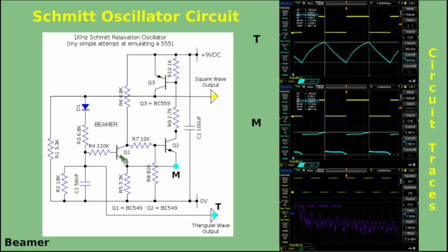And that is very important because it shifts the trigger level on the base of Q1 in a hysteresis way. If we look at the two legs of Q1 and Q2, that is the series resistor loads on the collectors of each, you'll notice this is a series of 2.7K plus 1K, which is 3.7K, as opposed to this collector load of Q1, which is 6.8K. There is approximately half the resistance load on Q2 as there is on Q1. And that is why there is a difference between 1.5 milliamps, which is this path here, and 0.85 milliamps going through there. And that is reflected across R5.